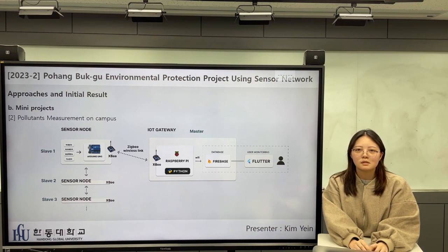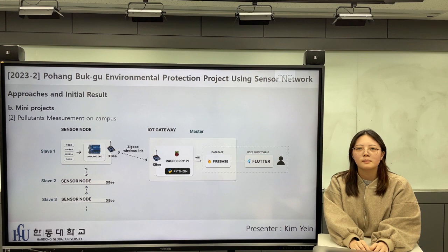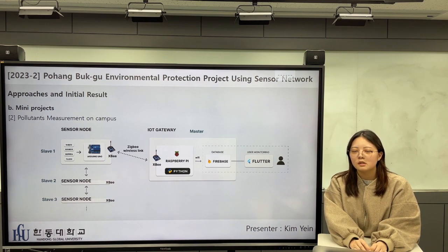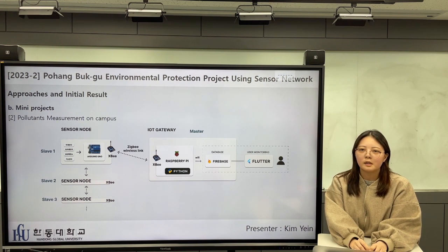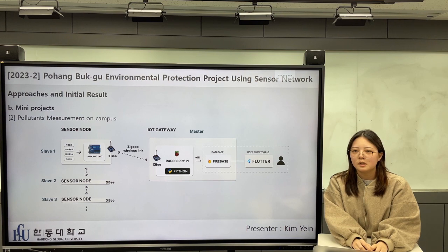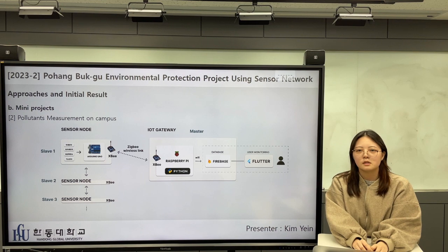We placed the sensor node in those locations and stored sensor data in the database every second. Arduino gets information from the attached sensor through serial communication. Arduino communicates with another Arduino or Raspberry Pi using the ZigBee protocol. The sensed information can be transmitted in a structured format. The network protocol that we use is ZigBee, which has the benefit of low power consumption and ease of implementation.